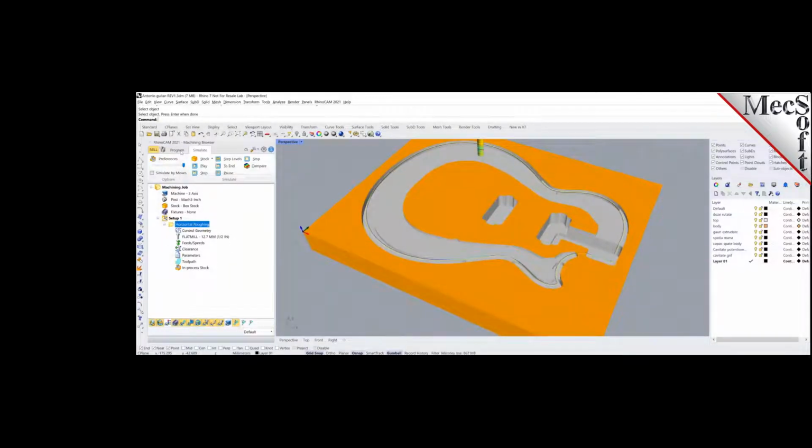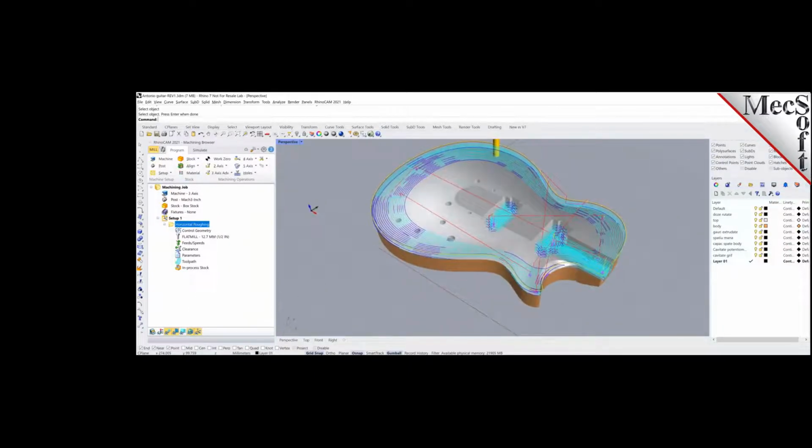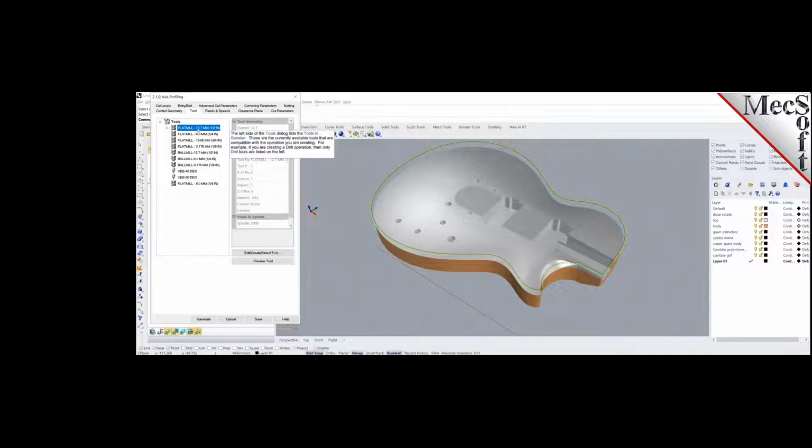Then I can run an outside toolpath. I can actually do a 2D profiling toolpath. Pick that and select that. Go outside. So let me do that. I'll do a profiling. Drive region, I've selected that drive. Select my tool. I'll probably select the big tool.